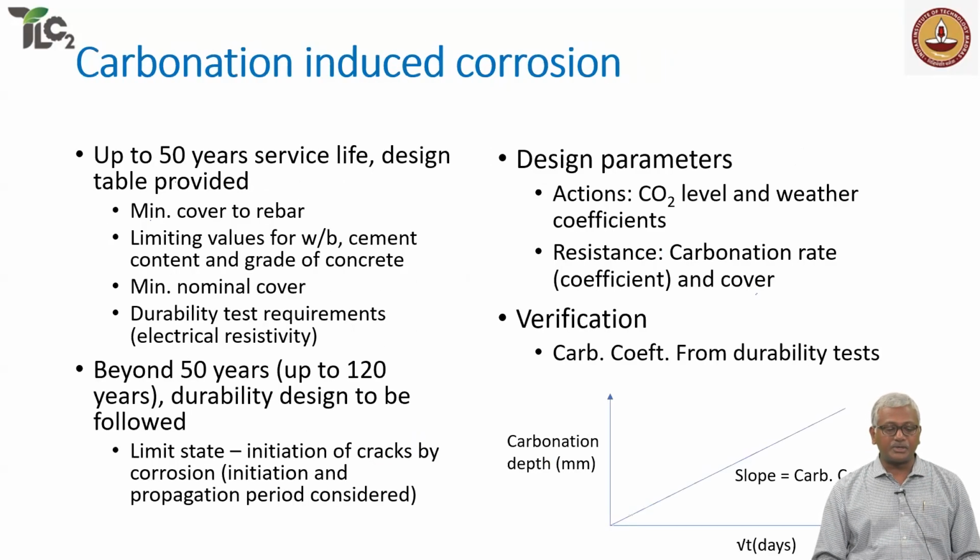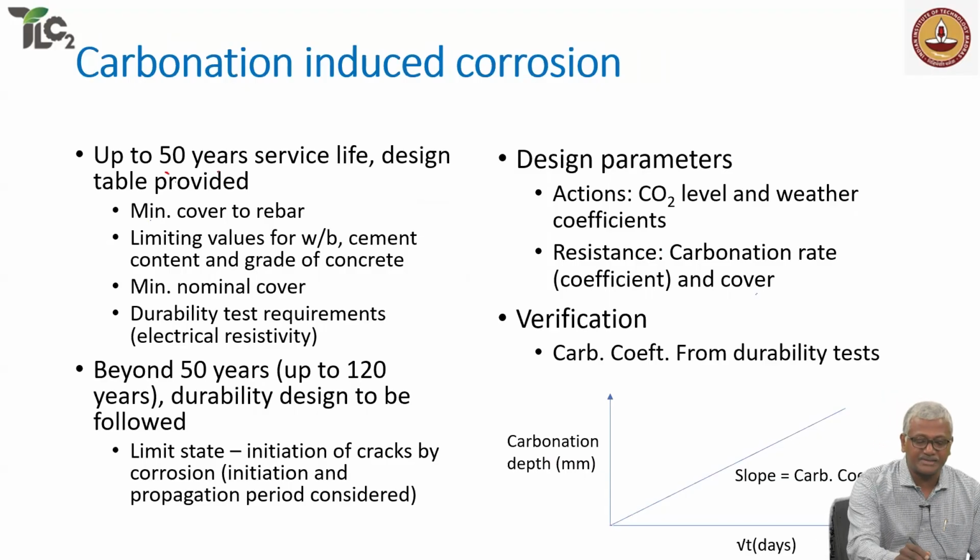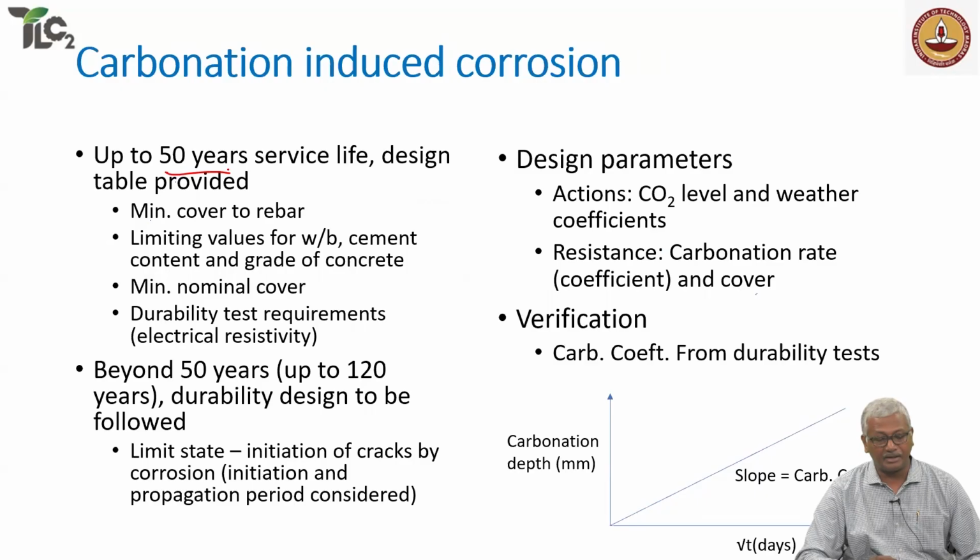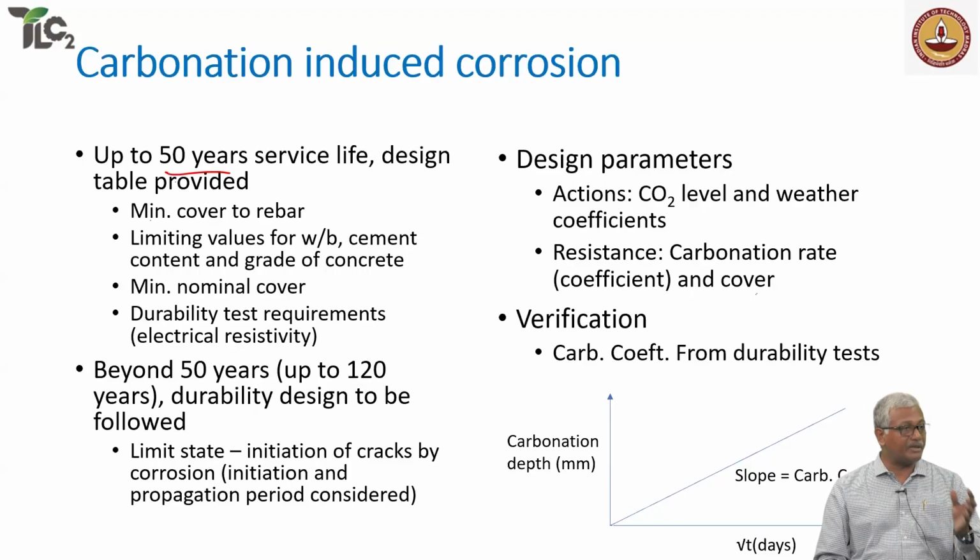So in carbonation induced corrosion, they are looking at prescriptive design for less than 50 years design life. Right? They're looking at minimum cover to rebar, limiting values for your water binder ratio, cement content, minimum cover, nominal cover, and a durability test requirement in terms of electrical resistivity. This is for 50 years or less. But when you are beyond 50 years, the IS 456 will say that you need to do a durability design.